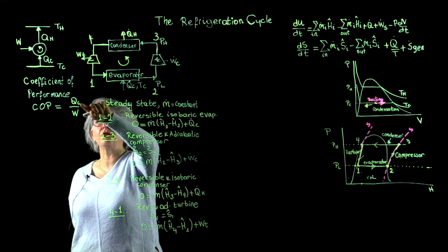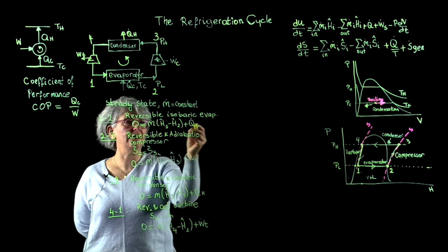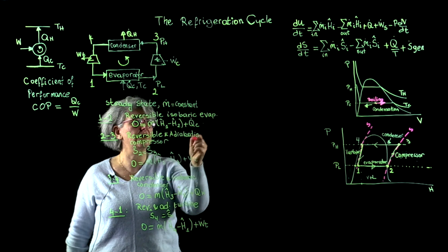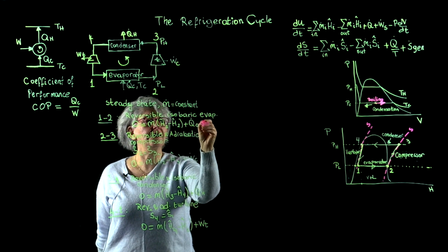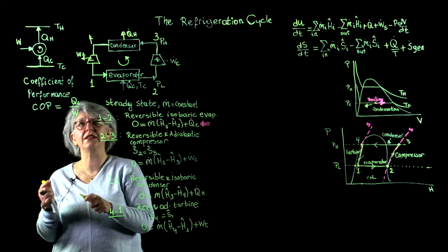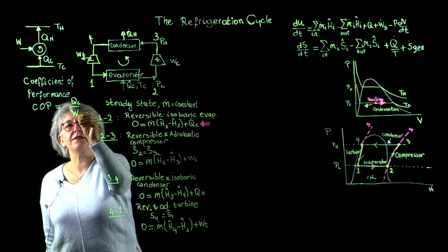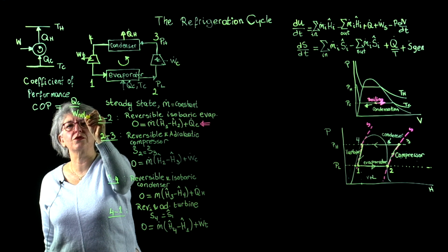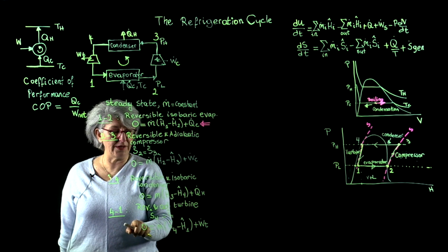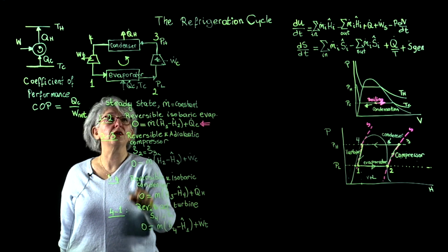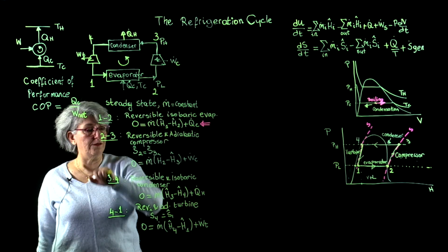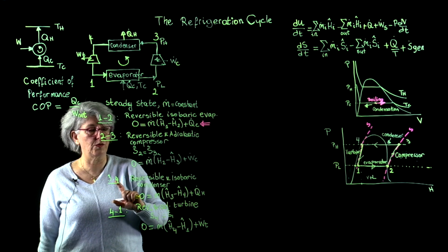What I need to remove is Q sub C. So this is one aspect of my coefficient of performance. The other is work. This should be the net work, right? For this Rankine refrigeration cycle, it is the net work. So net work is going to be the work that I did in the compressor and the work I obtained from the turbine. It's the summation of the two.